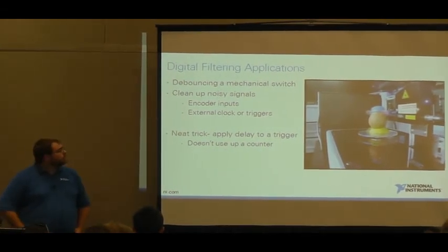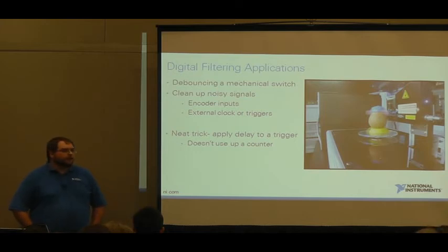Some other uses for it, we can also debounce a mechanical switch. So if you just take a standard mechanical switch, it's nice to think of it as a straight off to straight on, but it's never that simple. As you depress the mechanical switch, it's going to bounce a little bit. And so when we read its output, it's going to have many, many pulses instead of a single clean rising edge. Another trick we can use digital filtering for is applying a delay to a trigger.